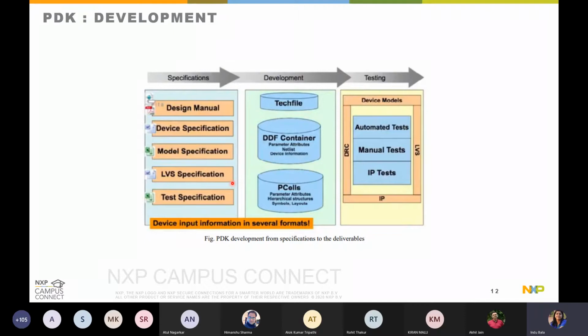Then the LVS specification defines what you want to compare when you are comparing your schematic versus layout. And the test specification: how you want to test your PDK or overall devices or the integrated flow of the PDK.